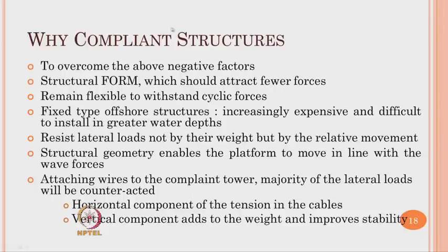The word compliant stands for flexibility or movement. Structural geometry enables the platform to move in line with the wave forces. The attaching wires to the compliant tower can counteract the majority of lateral loads by their horizontal and vertical components. The horizontal component of these guide wires or cables will alleviate the horizontal forces, whereas the vertical component will take care of the additional weight and improve stability.